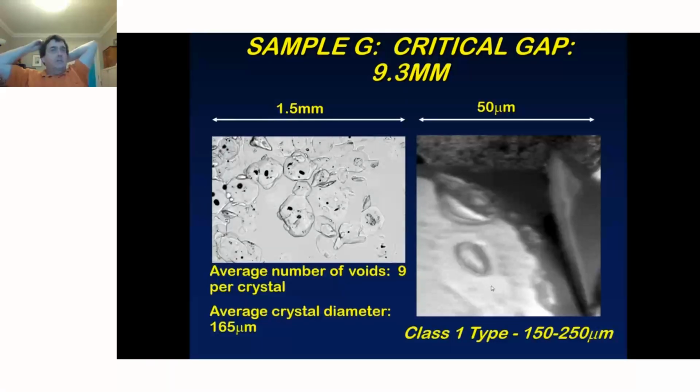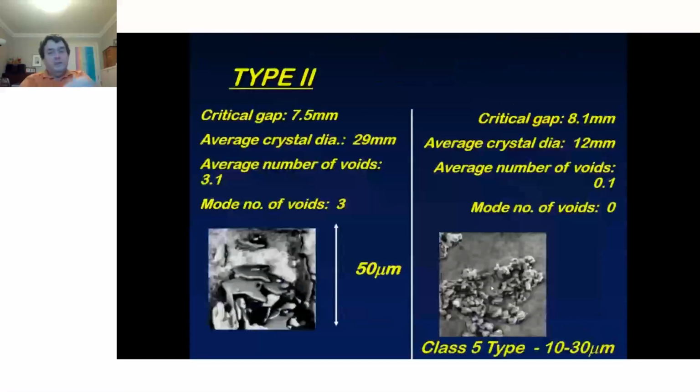In this case, it was ultimately found that it was not the voids inside the crystal that was important, it was surface defects. The number and density of surface defects on the outer surface of the crystal was the controlling factor. So if you wanted to make the material higher safety, less chance of reacting, you had to control surface crystal defects and not internal voids in the system. And we showed that for a range of size as well.